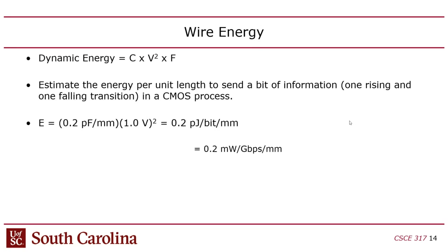So you basically have an envelope, you have a limit, and to stay within that limit, even in the face of increasing amounts of capabilities or number crunching and operations per second, you need to bring that voltage down. But you bring the voltage down, and you get that voltage down to near threshold, and all of a sudden you now have leakage. You got a lot more leakage current.